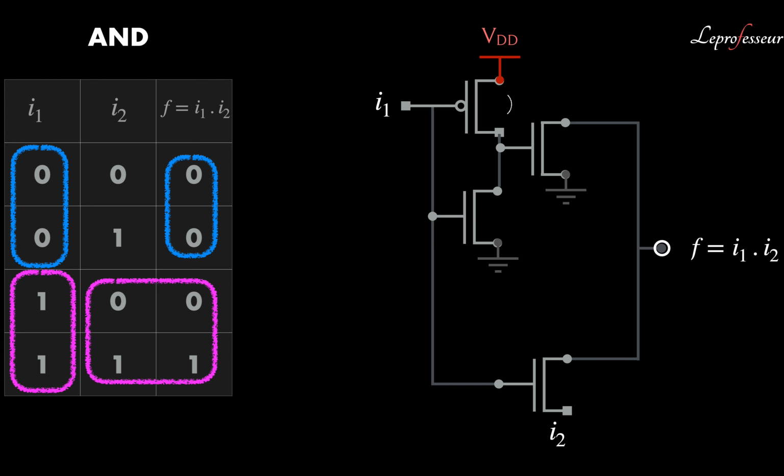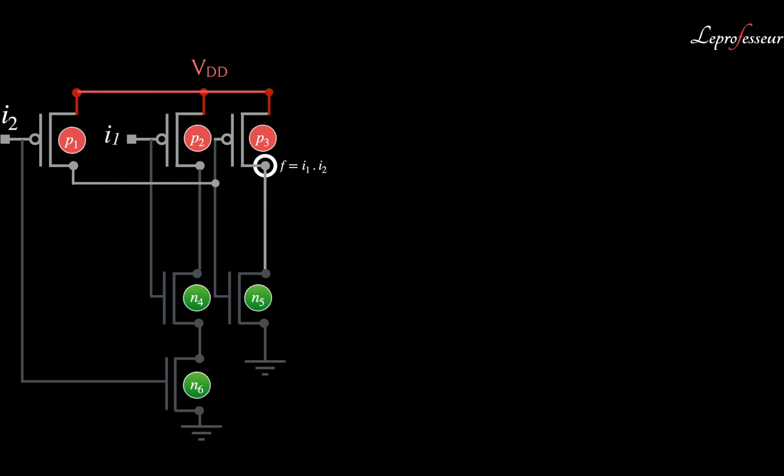Very good. So now let's look at how many transistors we have used here. We have used one PMOS and 3 NMOS transistors in the whole circuit. We have a total of four transistors. And if we don't use the pass transistor concept, as we have seen in the CMOS circuit case, we will have to use 3 PMOS and 3 NMOS.